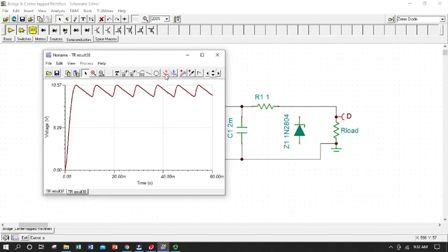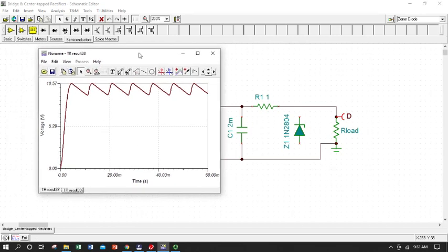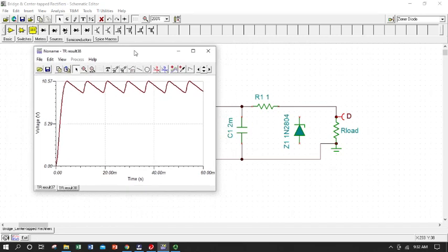So it would be nice to have a power supply whose voltage output, its average output, excuse me, didn't vary with the amount of current we wanted to draw with the circuit we're powering with it. Now that gets pretty annoying when we have a power supply from which we want a certain average voltage. So one of the ways that we can take care of that is to use a property of a Zener diode, which is the fact that it has that very, very stable reverse breakdown voltage. And it's designed to work in the reverse breakdown mode.